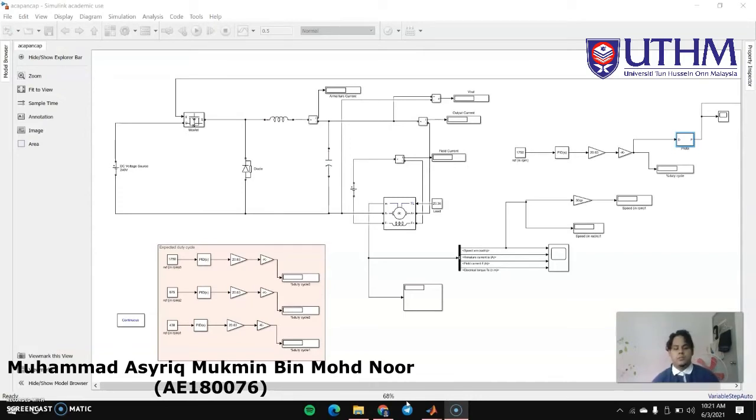So first of all, as we know, pulse width modulation is a fancy term for describing any type of digital signal, and it is also used in a wide variety of applications. In a DC motor speed controlling circuit, PWM varies the motor speed by simulating a reduction or increase in supply voltage, right? So today I will show you the relation between the PWM and the buck converter, right?